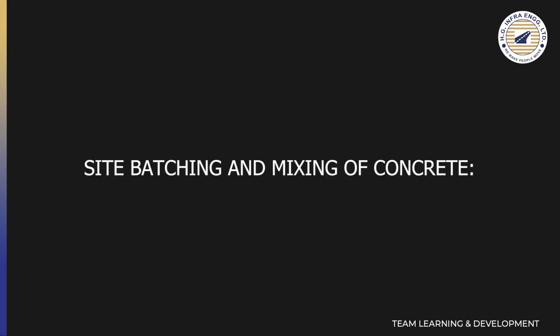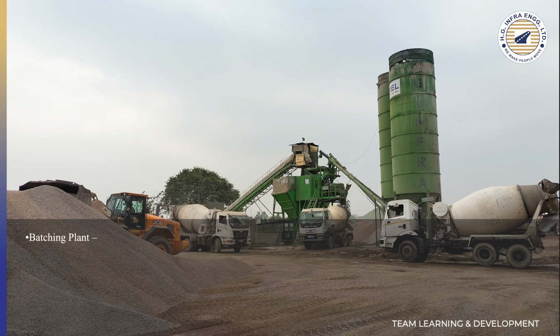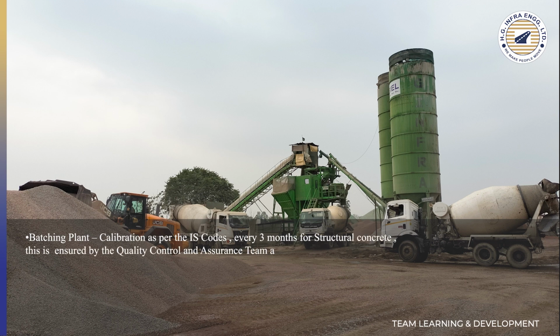Site batching and mixing of concrete. First, batching plant. Calibration as per IS codes every 3 months for structural concrete. This is ensured by quality control and assurance team at the project site.